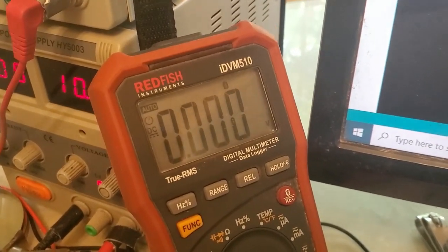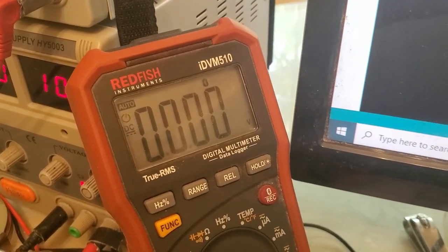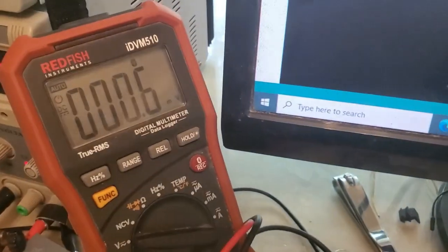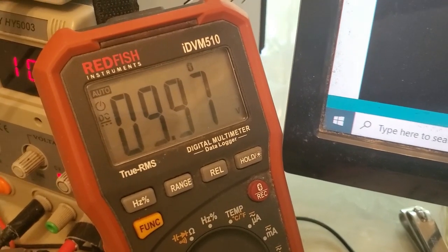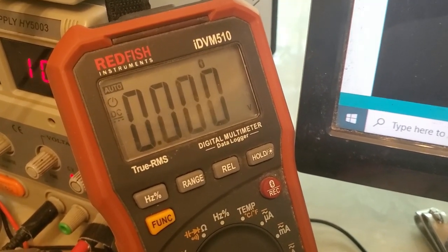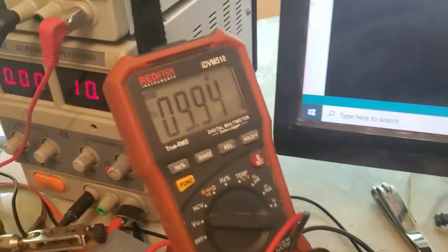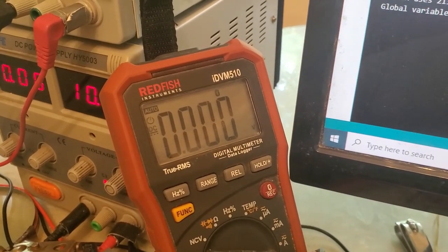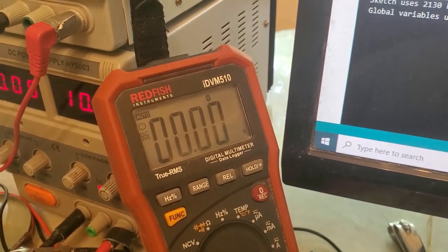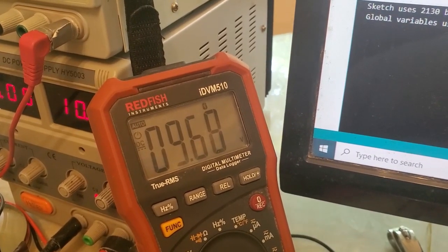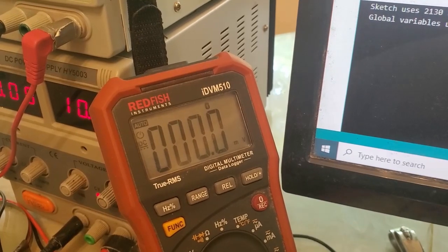Let's make that 3 seconds to see how quickly it discharges. So that's just showing how fast that cap leaks out through the meter. So you see, even with the 10 uF, it's becoming a little bit challenging to get a reading. You just have to look for that real high number there. It's actually 10.01, but I wanted it to settle at 9.99.